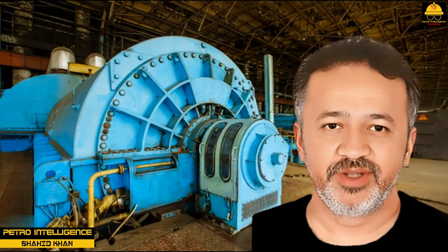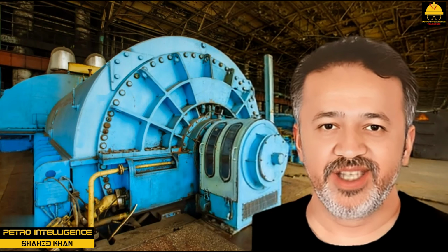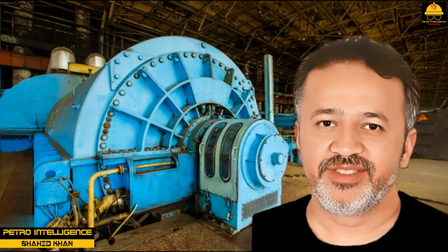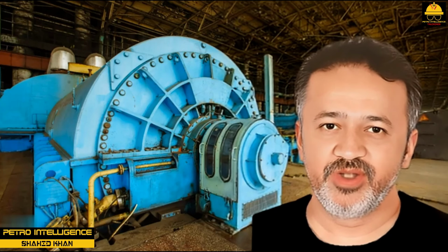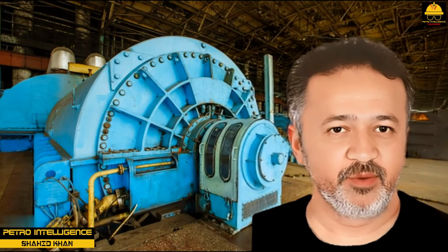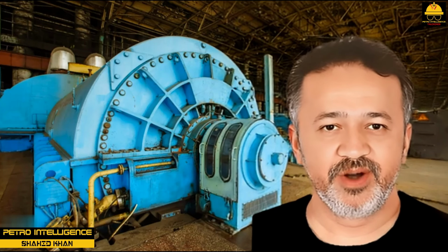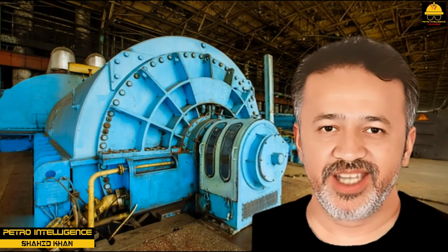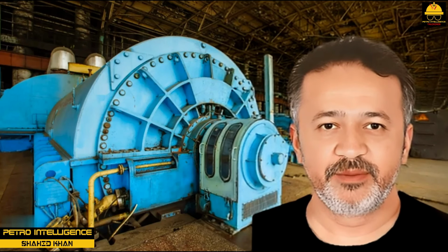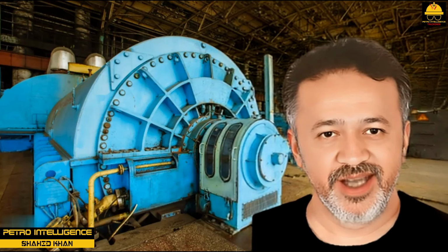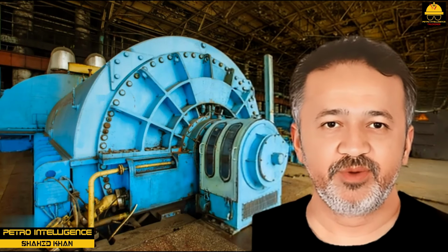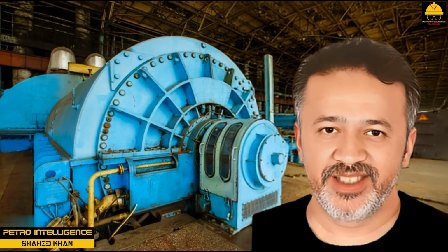Steam turbines typically are classified into the following categories: condensing, in which exhaust steam is condensed; non-condensing, in which exhaust steam is used in low-pressure steam applications; reaction, in which steam is discharged from a nozzle mounted on the rotor, and movement is a reactive response to the release of steam; impulse, in which steam acts upon the rotor to create movement; single-stage; and multistage. Most plants use the impulse design.